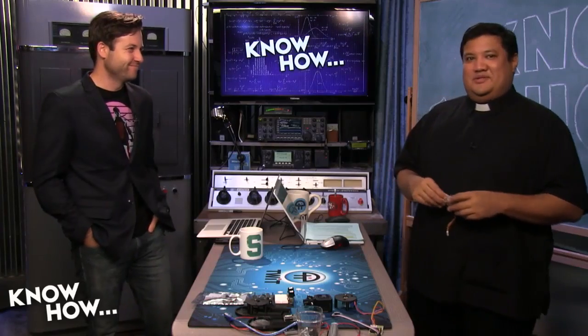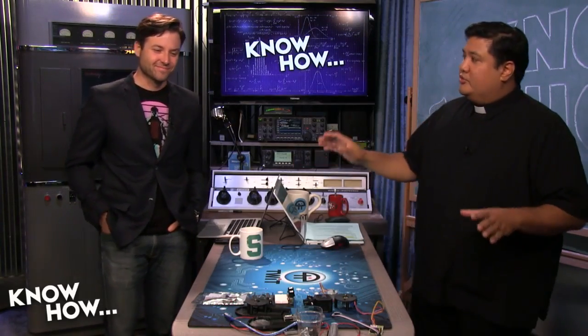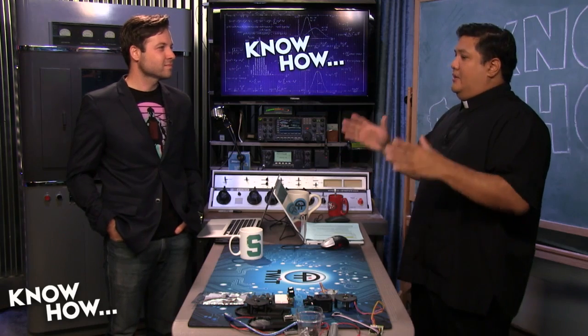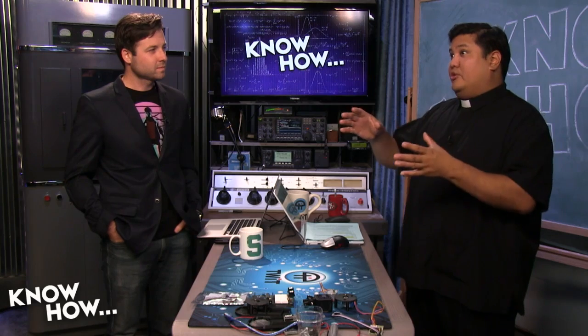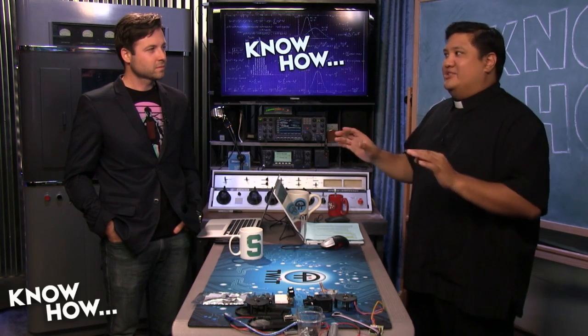Yeah, of course. The other thing that we're going to want to do is get a dedicated power source for the stepper motors, because eventually I'm going to be running 2 or 3 of these. I can't do that off of an Arduino. In fact, I could run one off of an Arduino, kind of. The problem is when it hits resistance, so when it has to torque up, it will draw exponentially more power, and that would actually blow out the Arduino.